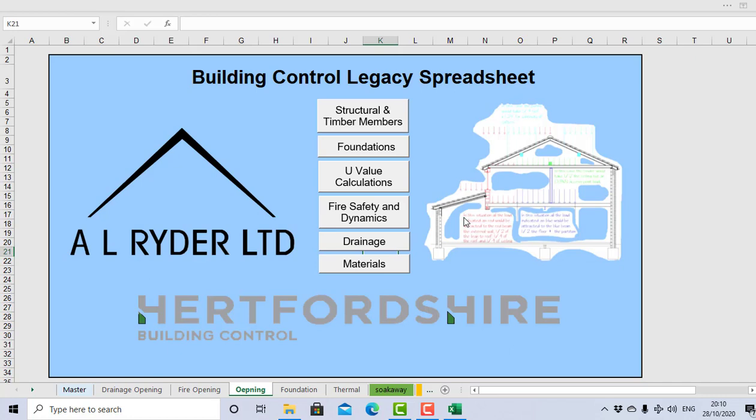It does U-value calculations through that type of roof, whether it's between and under or multifoils. It doesn't do over-the-top insulation, although I could quite easily put a sheet together to do that. So it does that. It does cavity walls at the moment, and it does flat roofs, warm and cold deck.